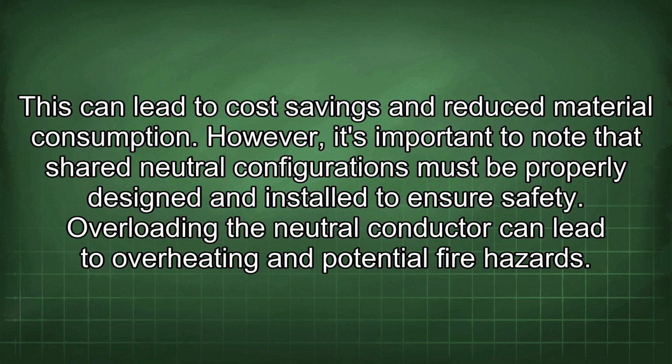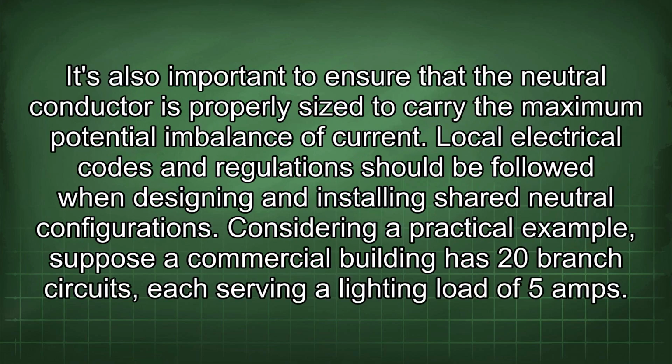However, it's important to note that shared neutral configurations must be properly designed and installed to ensure safety. Overloading the neutral conductor can lead to overheating and potential fire hazards. It's also important to ensure that the neutral conductor is properly sized to carry the maximum potential imbalance of current. Local electrical codes and regulations should be followed when designing and installing shared neutral configurations.